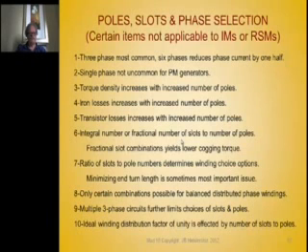The ratio of the slots to pole numbers determines the winding choice options for all 3 of the motor types that we're talking about here that use the same stator. Sometimes with certain designs, one of the most important elements in the whole design is to make the end turns short.